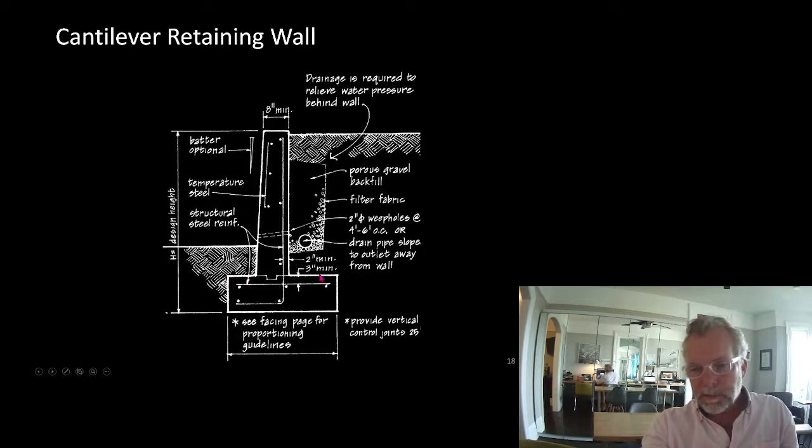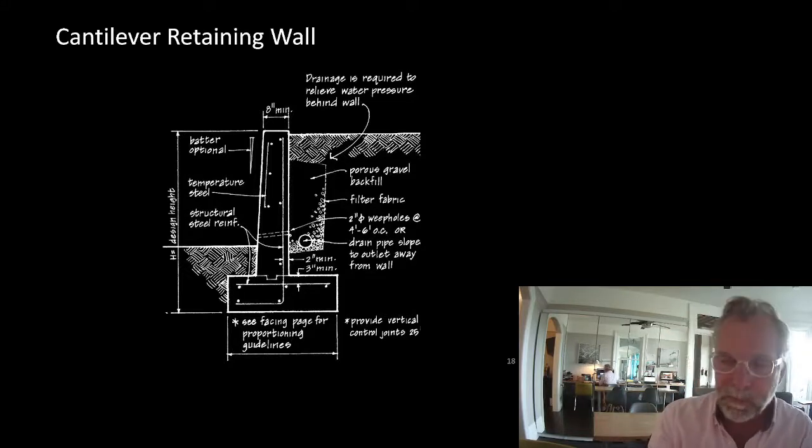Where we can put the footing under the high side, the proportions tend to be about 1 to 1.5. So if we have a 6-foot tall wall, we need about a 4-foot wide footing. Those proportions are about right. Remember when I told you that for a curb, 1 to 1.5 is about the right proportion. So that sort of follows through.